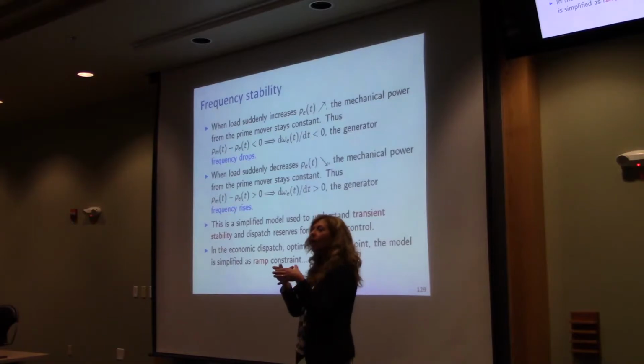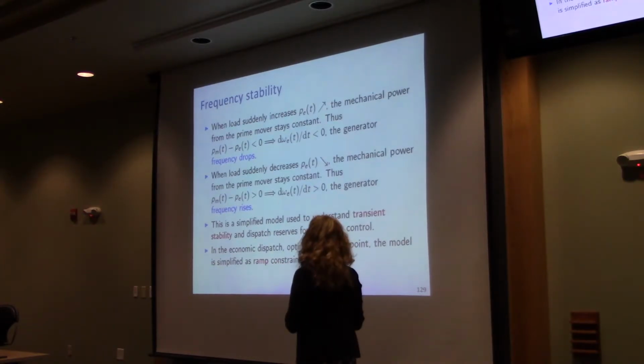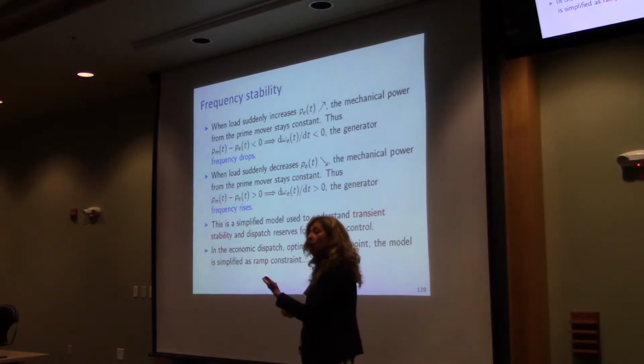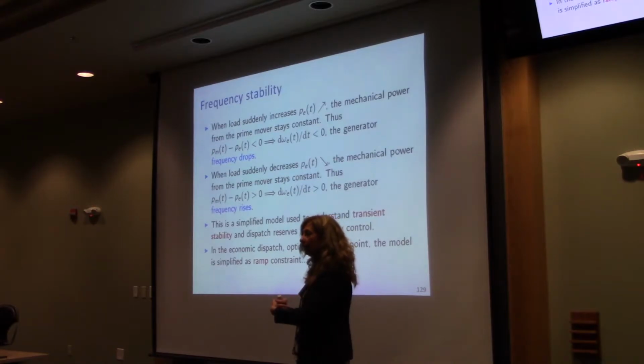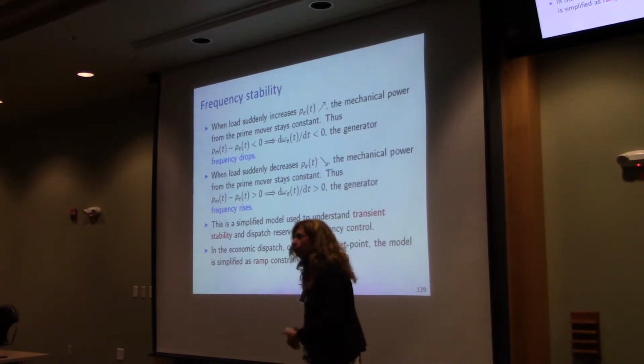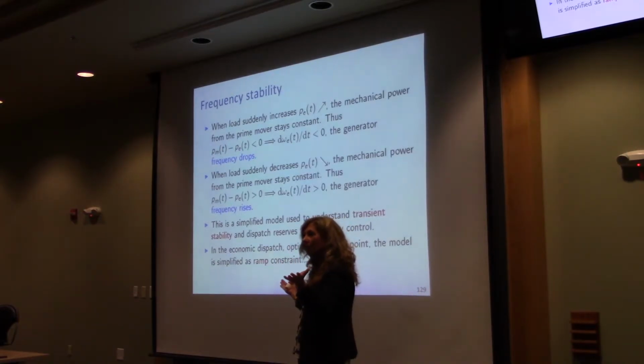We just are not going to try to get out of a kind of narrow region where we can actually analyze, linearize, you name it, right? A narrow region around that point. And by the way, most of the blackouts that happen, they happen because the system has something malfunctioning. There is no global awareness of how to change the set points to go again close to a stable point where the local control can bring you. And what happens is that you create these big oscillations among big generators that eventually lead these generators to disconnect, and there you go, you have a blackout.